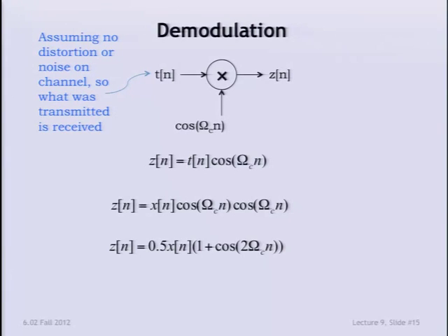So basically what you end up doing in one way of tackling that is you multiply by a cosine, you multiply by a sine, and by looking at the outputs of both of those, you can actually figure out what the right phase shift is. So that's a good question. It's not just phase shift. There's also time delays of propagation and so on. So it's a real issue. But let's just deal with the simplest case for now.